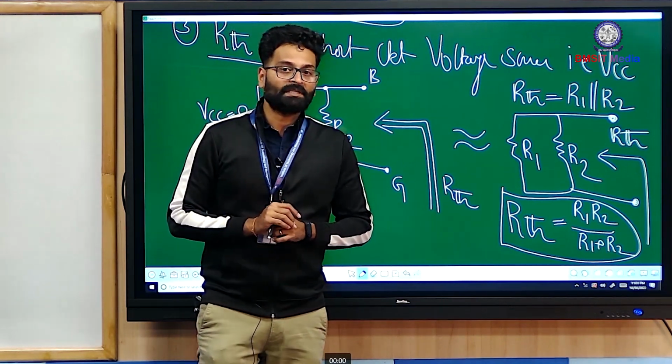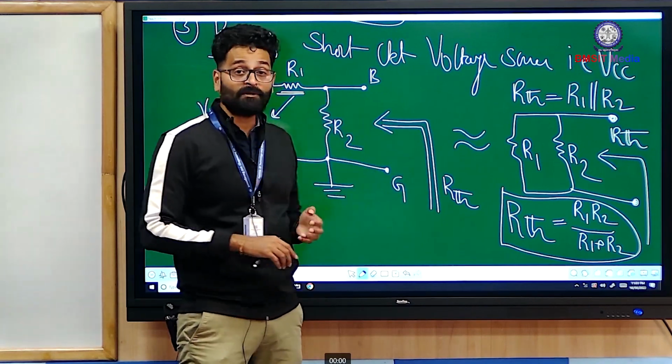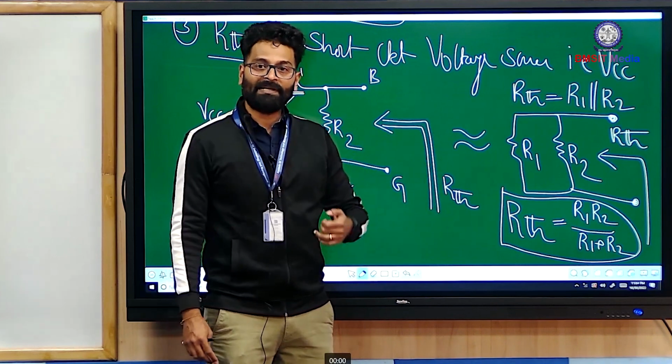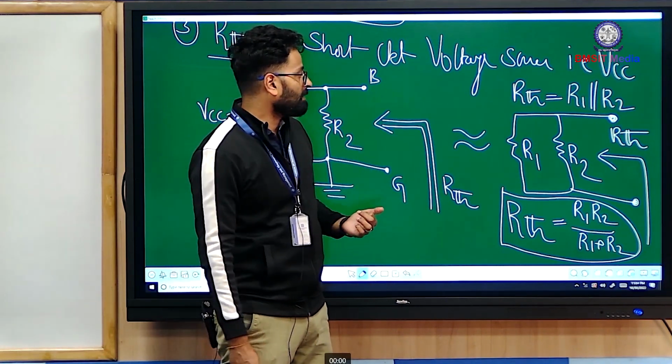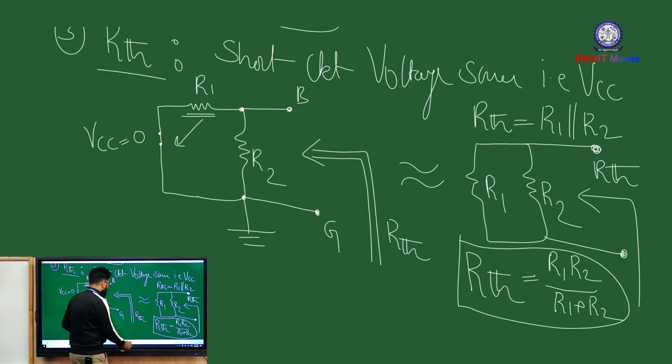And by applying Thevenin's theorem, all the resistors which were present in the network are converted to RTH, and the available voltage sources are converted to VTH. Okay. So once this is done, you reconstruct the network. In the sense, in the first step you had removed the load, right? Now you insert the load. Okay. So this is the last step.